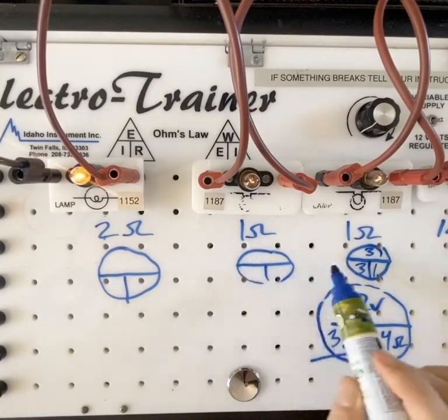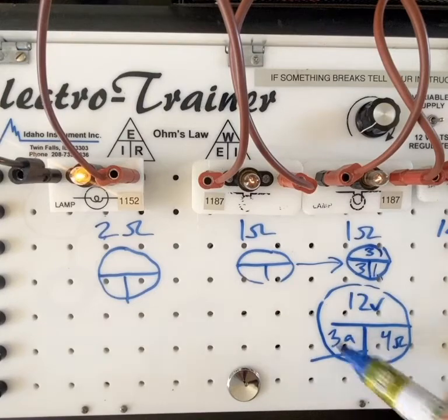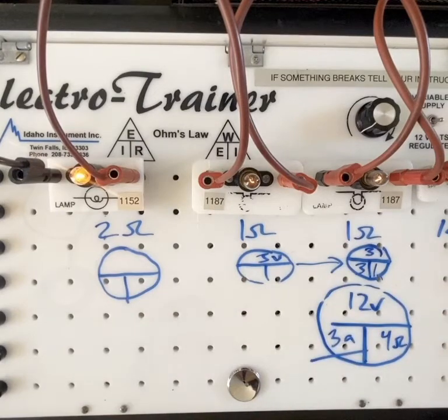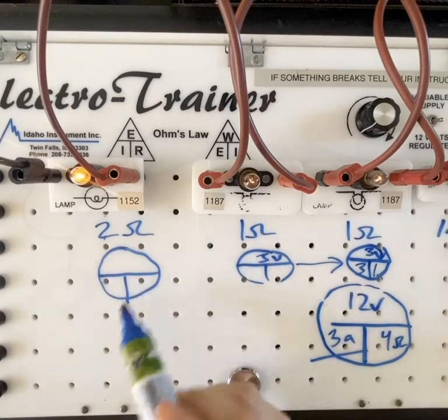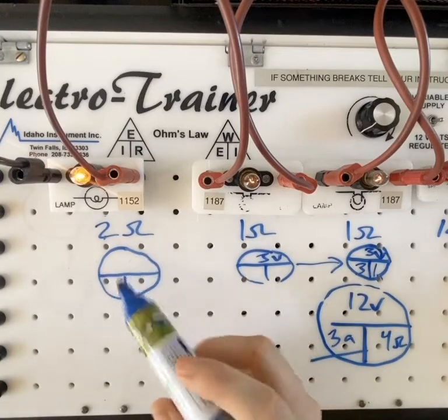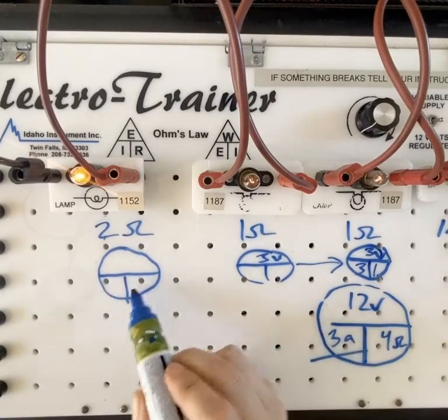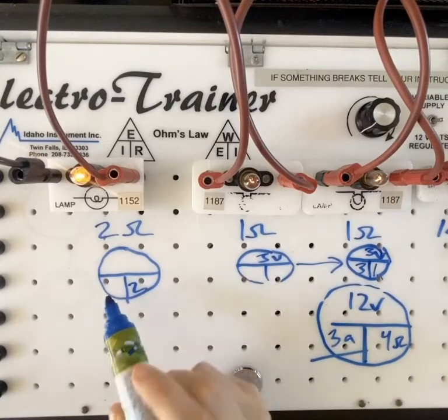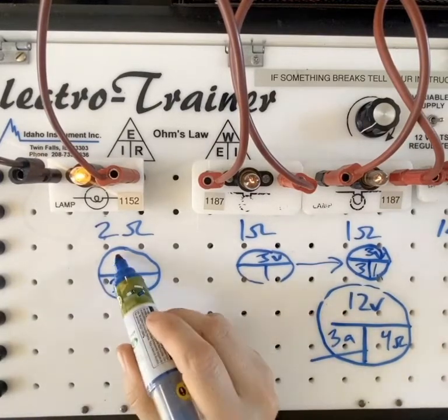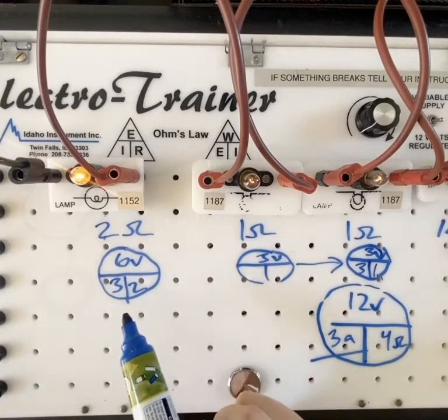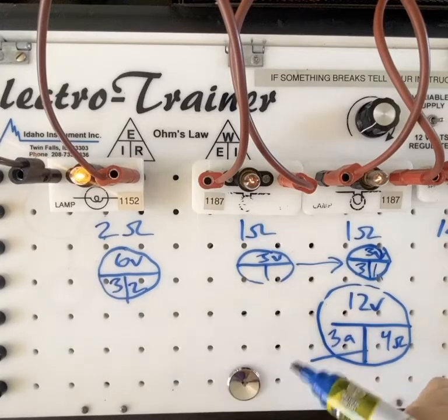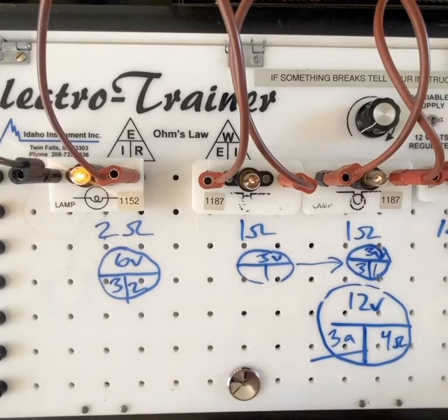Well, we know the math is the same because the numbers are the same. Amperage is the same throughout, and it's the same resistance value, so we know this one would drop 3 volts as well. If these drop 3 volts, 6 volts together, so far we've got 6 volts coming out of here. If you were going to guess, we're probably going to finish that up here, all those leftovers. So let's calculate that out. We've got 2 ohms, right? 3 amps again throughout the entire circuit. 3 times 2 does prove to us that this one does have more resistance, and therefore it's going to use up the most amount of voltage. So that is our series circuit in a nutshell.